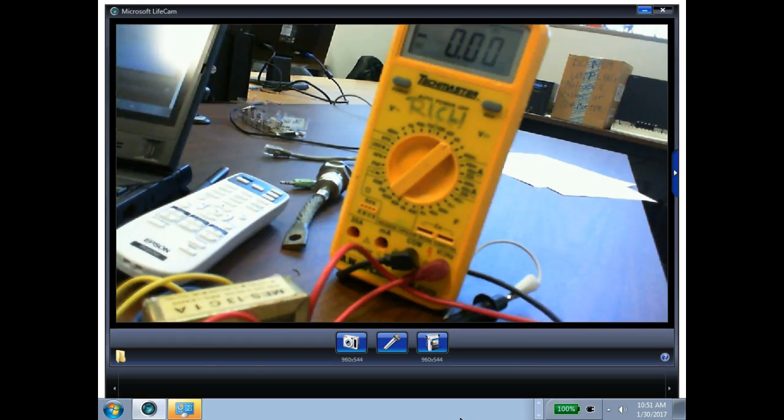So I'm going to move it over to the cathode side, and we're measuring 5.7 volts. We calculated 5.4, so there's only 300 millivolts difference between our calculated and our measured. Not bad, right? Of course, we know why it's different, because it's not exactly 110 volts on the primary, and we're not pulling 1 amp out of this thing.